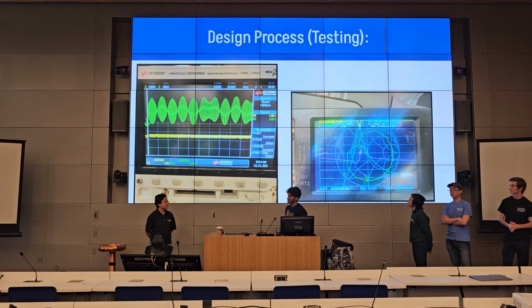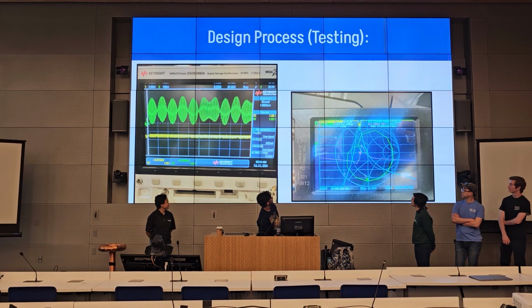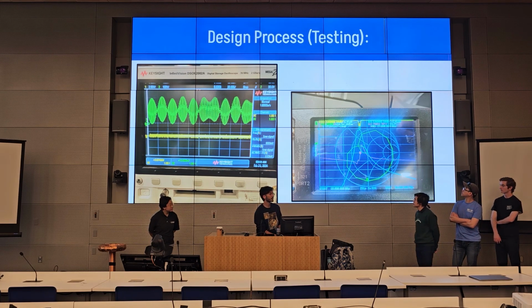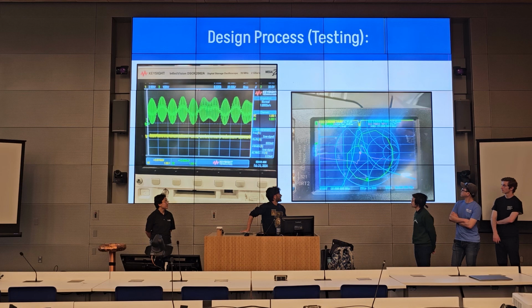And over here on the right is a zoomed in picture of a nanobeam. Sorry, your left, my right. I mean, your right. And again, you can see this for a filter. In the blue curve, you can see it's S21, and that's basically telling you the forward feed through gain. And we can see that, hey, it's a bandpass filter, and it's at 27 megahertz, where we expect it to peak. So that's great. S11 is low, that's acceptable. And this is another way for us to verify our theory.